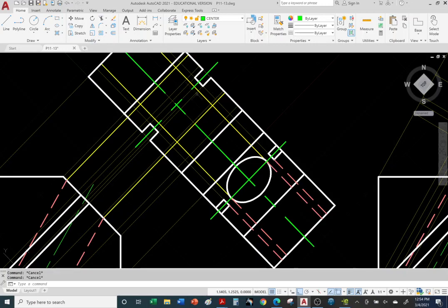All right, so our ellipse is going to fall between, or you can see inside of this square, right? We know because it lines up with the ellipse here, and it lines up with the red hidden lines representing the hole. So the ellipse is sitting inside this box. It's actually going to touch the box. And our center is where the green center lines intersect.